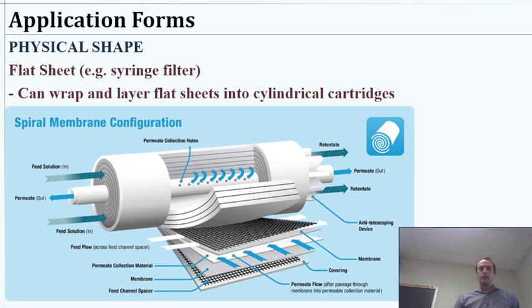Okay, so that's pretty neat, and it gives a little bit of detail here, probably a little small to read each of the bits there, but you can see that they've got these permeable support layers that are kind of like mesh grid that will allow water to flow through between the layers, and then you have a membrane in between and a different type of material to collect the permeate and convey that through. So that whole system is pretty neat.